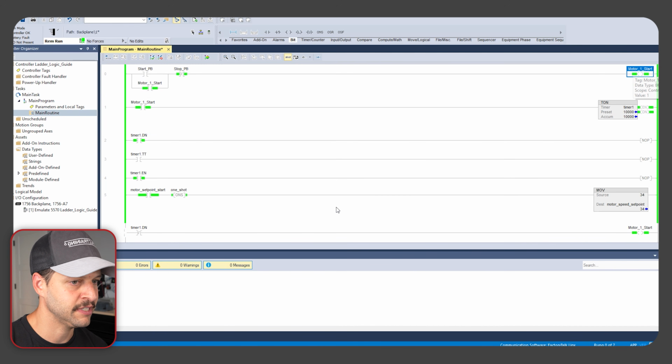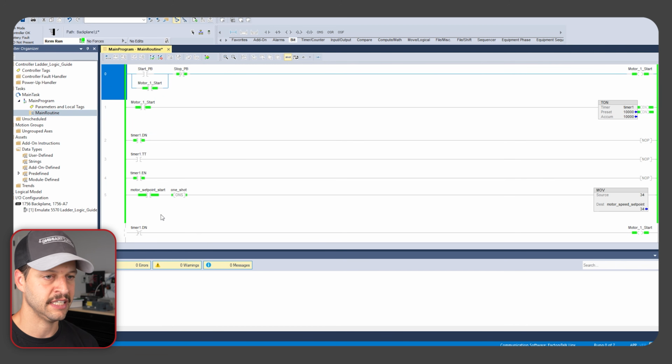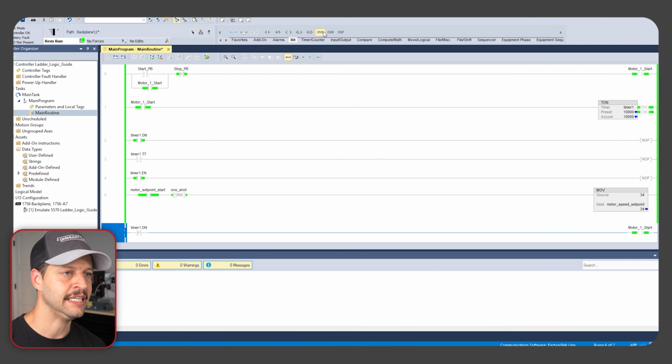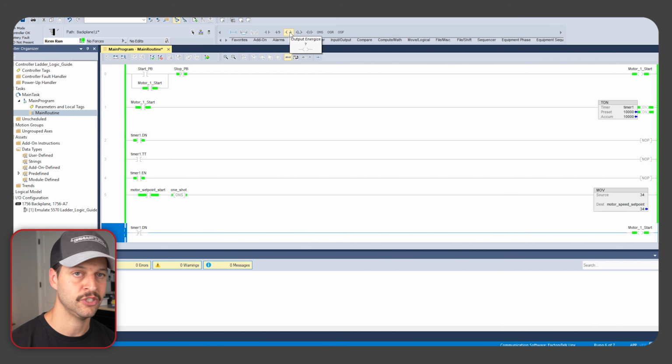This is going to be controlling it, and this is going to be controlling the same output, and they're going to be conflicting and battling back and forth. It's not pretty. You can cause big problems by doing that. So never use a tag more than once as an output. Now, if you're using the latching output and unlatching output, you can use one of each, and that's fine. One latching, one unlatching, but you don't want two latching, two unlatching, etc., and you definitely don't want 2 OTEs.